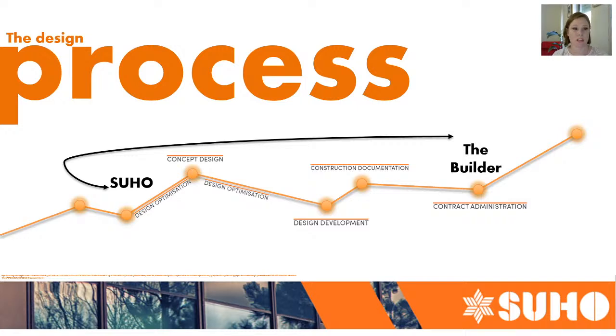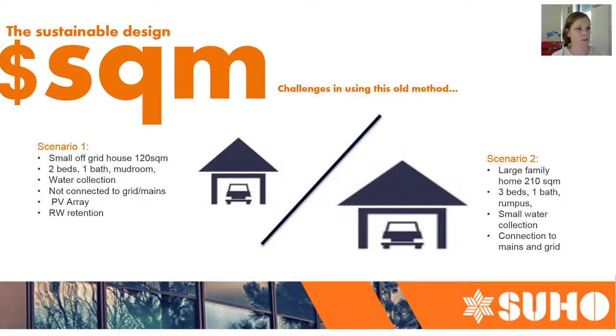of insulation. If it's going to be a super insulated building, then we might do a WUFI assessment to work out what the implications are of sweating of certain materials, or is there condensation building up and certain things like that. We might use FirstRate5 to particularly target areas that need more heating and cooling, so that we have a much more uniform performance of the building overall. So it's about having that dialogue.